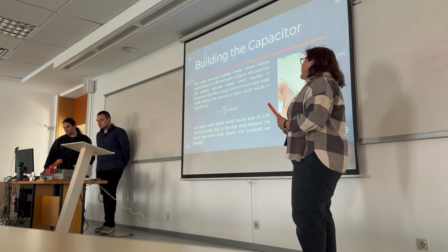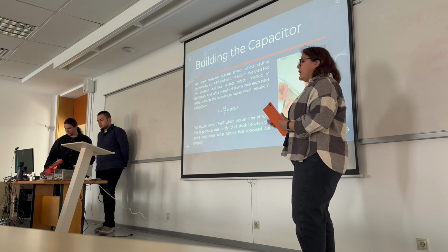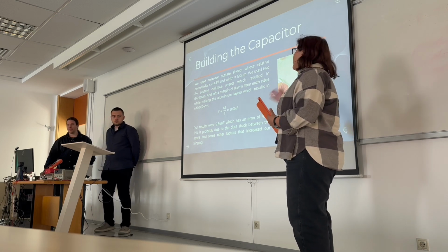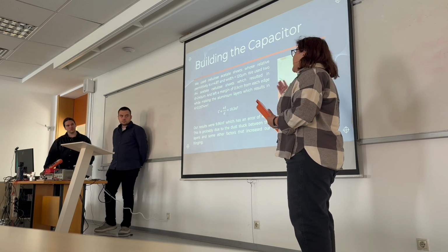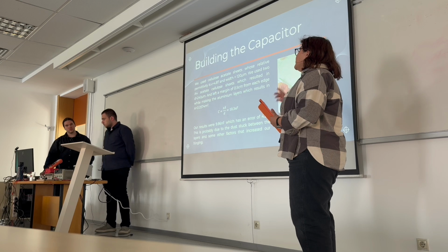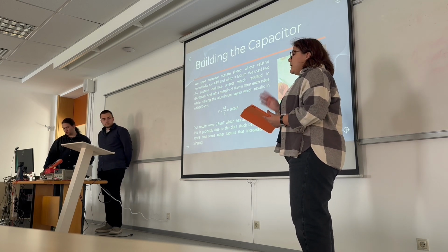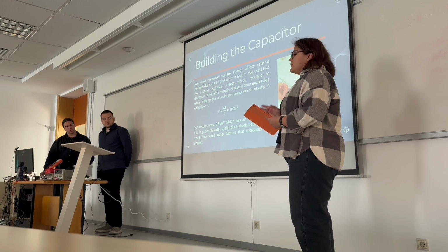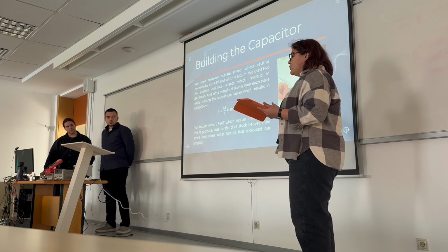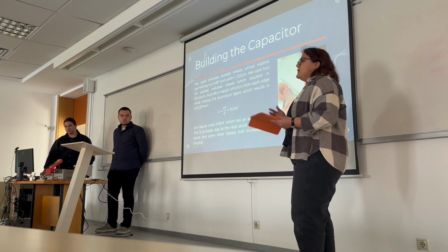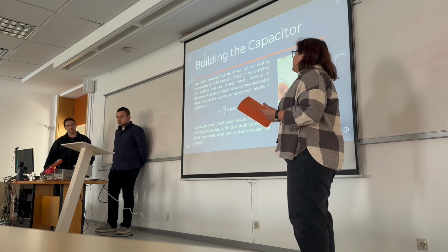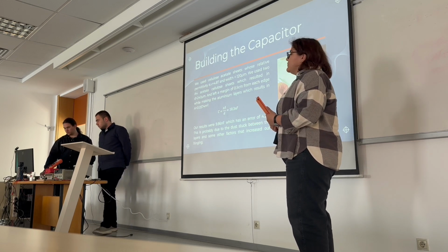Also, we use aluminum layers, leaving a 0.5 centimeter margin from all of the sides, and the area resulted in 0.057 square meters. We place the two A4 cellulose acetate sheets between the aluminum layers, and the distance between the capacitor plates is measured to be 240 micrometers.